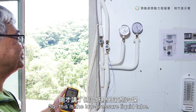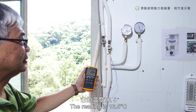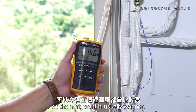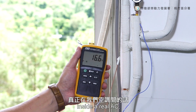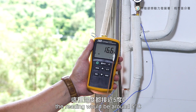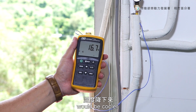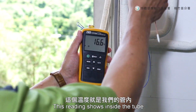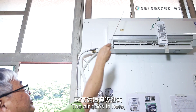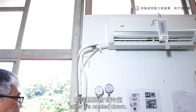So this is the low-pressure liquid tube. The reading is 16.5 degrees. It's a huge space where we film, so the refrigerant is usually warmer. Inside a real AC, to reach the set temperature, the reading would be around 5 degrees, so that the temperature in the room would be cooler. This reading shows inside the tube how cold the liquid refrigerant is. The air goes in here and comes out here after it's cooled down.